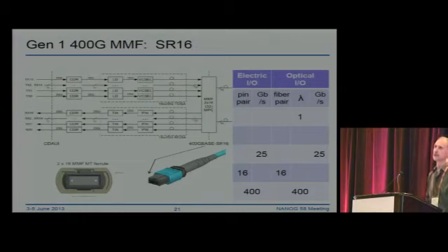MPO, all these parallel fiber connectors that you use to run bulk links across the data center have been by 12. The by 12 is a historical artifact from when people would efficiently pack copper cables. It's sort of like stacking oranges. But we're trying to move to by 16. So this connector was developed by US Connect, and you'll see that for 400G. Facebook now has this Open Compute initiative. They worked on a parallel connector with Corning. That's a 4 by 16 connector, so you'll see the by 16 more frequently now.